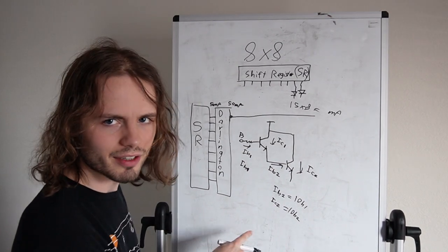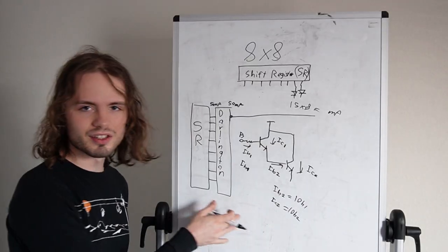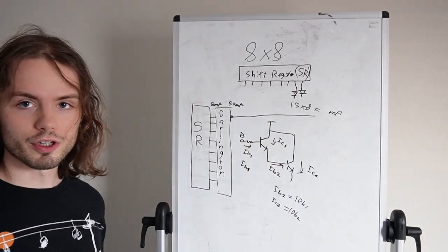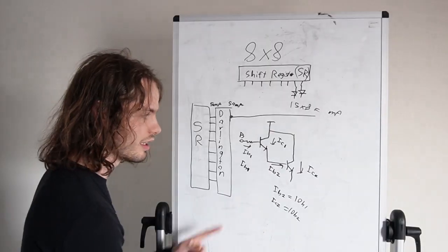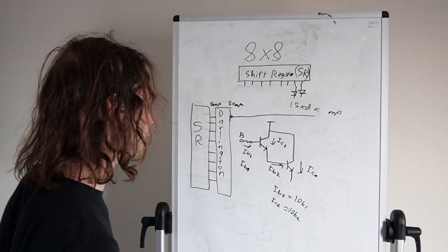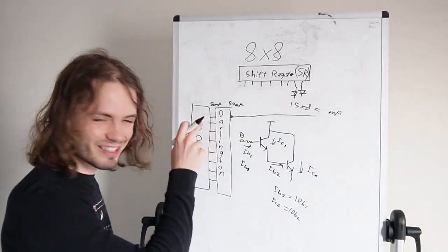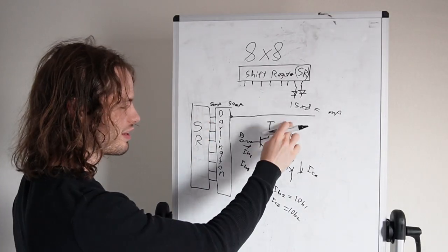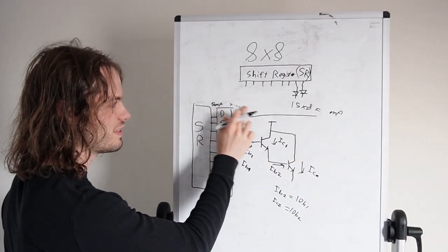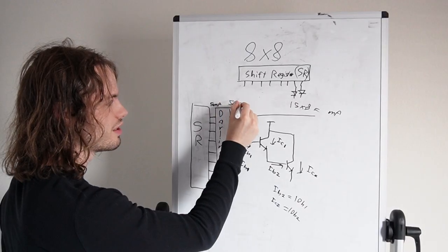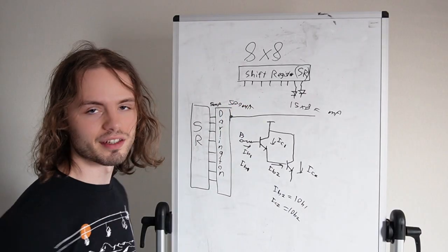So yeah, okay, I may not be drawing big enough, but the point is you can get a lot more current dumped through it when you use it in this format, and this is called like a Darlington. So by driving a Darlington rather than just a regular transistor, we can 10x this. So instead of 50, it's like 500 milliamps, which is enough for our case.